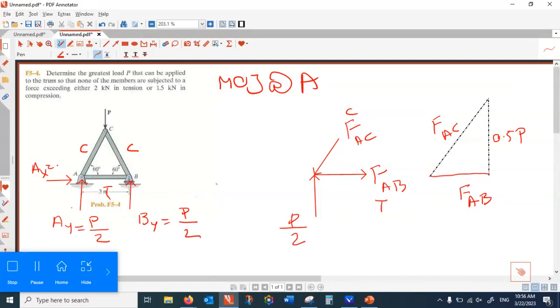All right? Can you visualize that you made a structure like this one and then you're pushing it? What happens to the AC? AC becomes shorter or becomes longer if you apply this load? You made a wooden structure. It has a wheel. It's free to move at one leg. The other leg is fixed. So you push this one. What happens here? Are these verticals going to be shorter or longer? Shorter, because they tend to become shorter. They're under compression, and the horizontal leg, because of that wheel, tries to escape. That becomes longer, tensile.